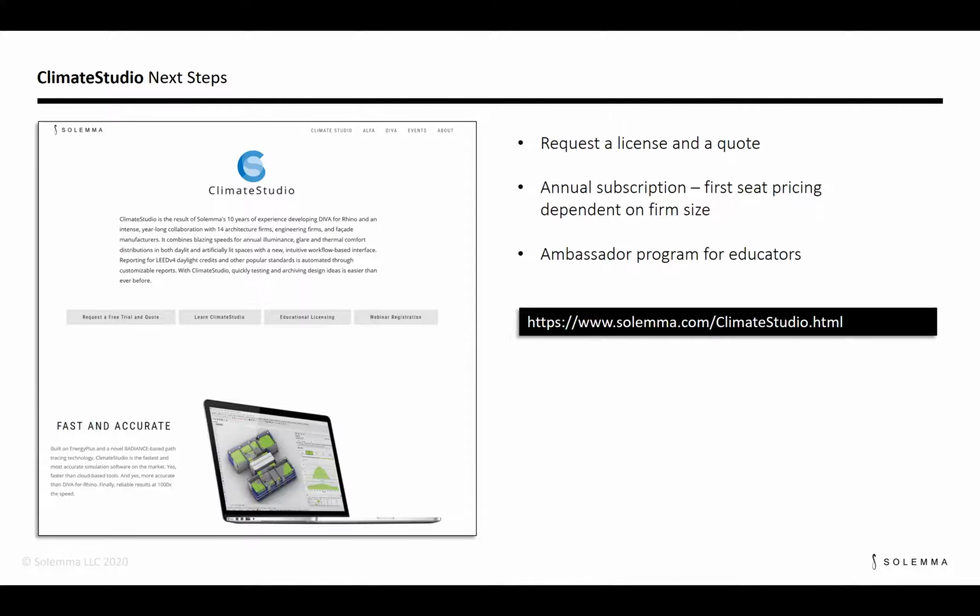The tool defines as many different shading groups as are necessary. So if you have different window orientations, the upper and lower parts of the windows, different shading systems, electrochromic systems, we implemented the data from some of our executive members. That's all possible. There's no limitation. In terms of the control of the shading system, we have the simple lead control implemented right now, but you can implement your own comma-separated value schedule as well. And we'll be adding some more generic controls as well, based on temperature and so forth.